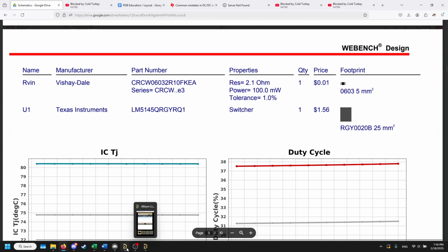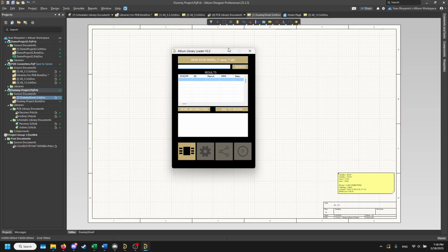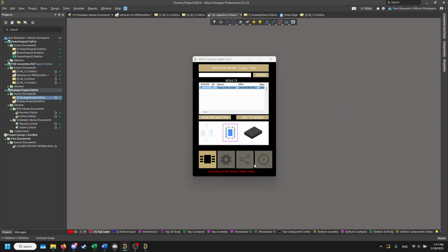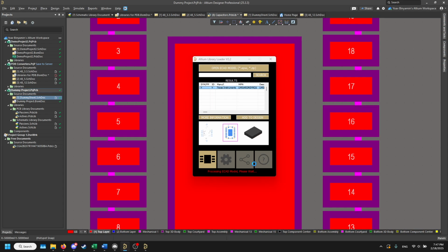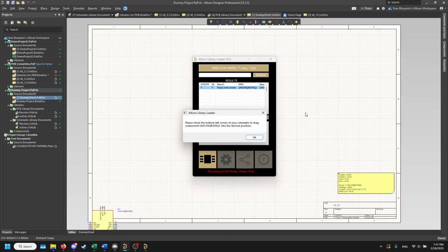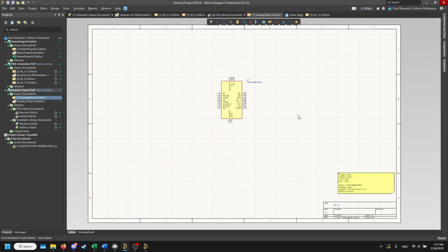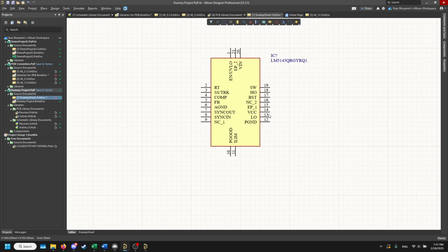So if we have the tool, this Altium library loader, which you should already have, you can type this inside, and you're gonna search. And for these kinds of chips, it's gonna be easy because there's only gonna be one kind of design link here. You'll add this to the design. It does a very cool montage, right? And then here we have this thing in.